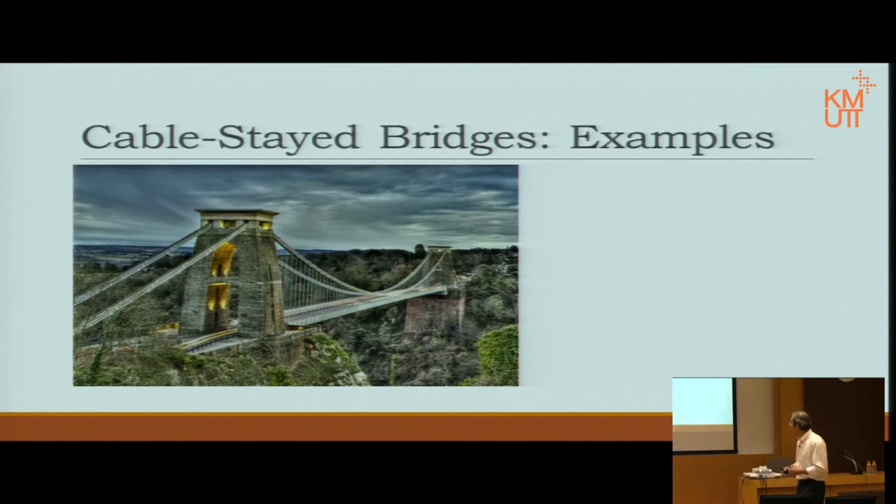This is probably one of the earliest models. Notice that the structure now has a tower and has the road or pavement. The span of the bridge is very, very long, across a cliff. Now, if the span is long, we have done the bending moment diagram before. We know that even though the load is the same, if the span is longer, the bending moment value becomes much higher. At one point, when it becomes so high, the cross section or the material we use will be so large, which is sometimes not appropriate or too expensive, so let's find another way to do it. In this case, we use cable to help resist, reducing the deflection and also transferring the load from the beam to some other part as well.